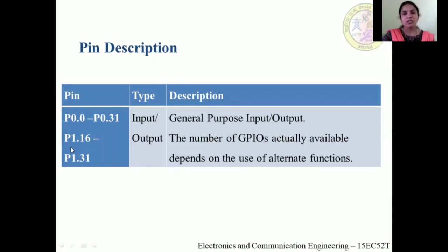In a real-time application, if you are going to manufacture any embedded device by using the LPC2148 IC, we have to connect some external peripherals. In the case of a computer, it can be a keyboard or mouse or monitor. In the case of a mobile, again a display unit or speaker unit or LED or memory. Those are all called external devices. Those external devices are connected to the LPC2148 IC by using these GPIO pins.